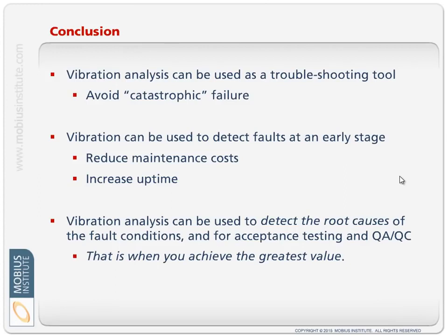Let's be proactive. Let's put a force field around the plant and use vibration analysis for acceptance testing. Let's test that pump and the motor and the fan as it comes into the plant, in agreement with the vendor, and we tell the vendor, if it doesn't pass our vibration test, we're not accepting it. Now you might think, why would you do that? Of course the brand new pump or the recently rewound motor, they're going to be in great condition, aren't they? Not always. And as soon as you accept that equipment, boom, it's your problem.